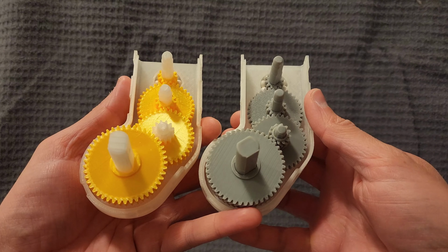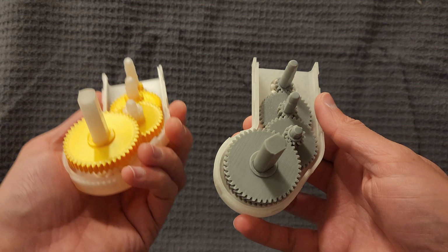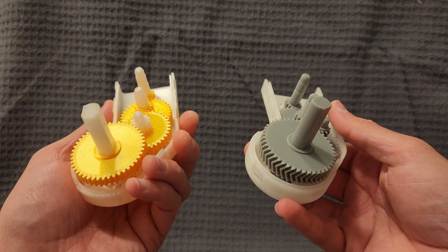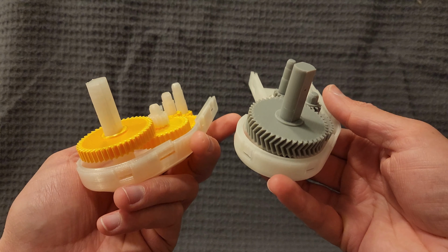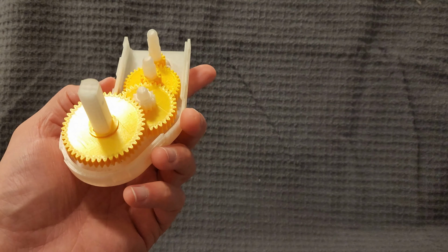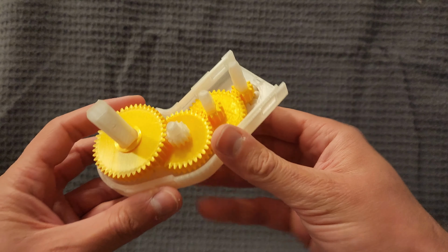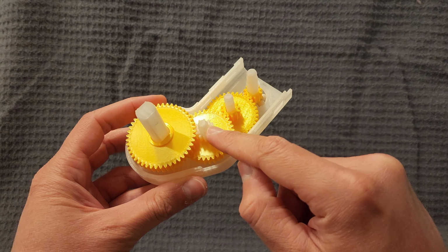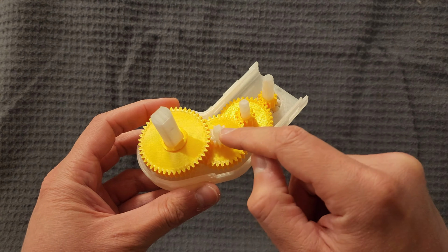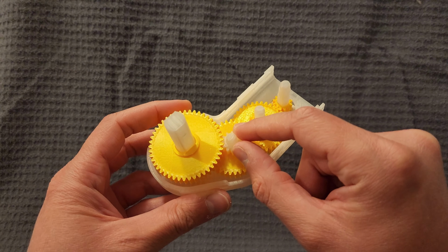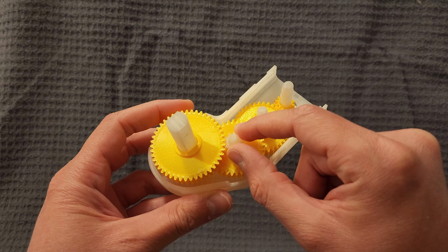The next change has to do with the gearbox design. You can see on the left the old gearbox and the new gearbox on the right. You may already see the big difference. The old gearbox had a flaw, basically where the small spur gear that you see in white here actually sees the highest amount of stress of the whole gearbox because of its size and also because it's on the first set of gears of the gearbox. And this was causing issues.